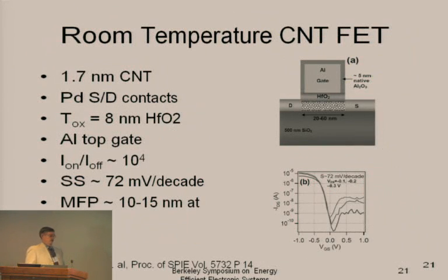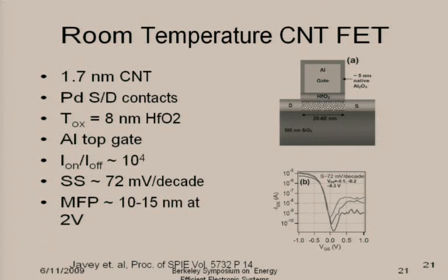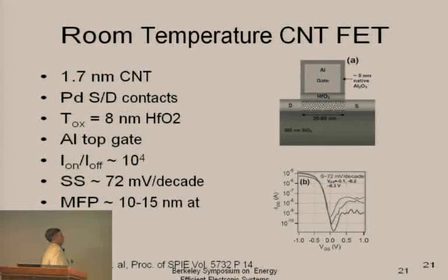So in addition to graphene, there are carbon nanotubes. And these are some results coming from Ali Javey, who basically shows a very, very promising carbon nanotube FET with some very nice characteristics. But this has to be done very carefully by selecting the nanotubes individually by hand and then positioning them and then very carefully attaching the source and drain.